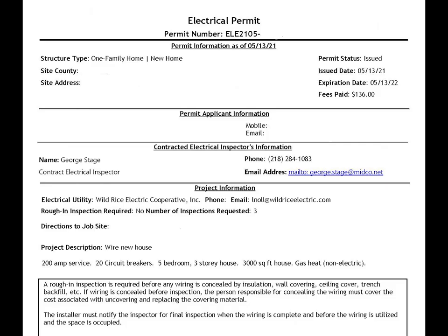The last inspections are the 2 electrical inspections, the rough-in electrical and the final electrical. The rough-in is accomplished when the studs are all still exposed and the wire runs can be seen throughout the house. This way, needed corrections can be made to wire size, number and placement of outlets or switches, if necessary.